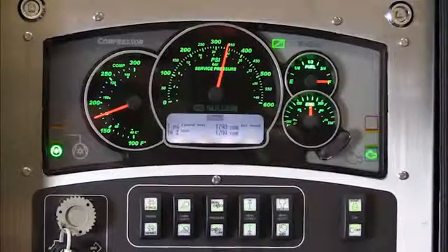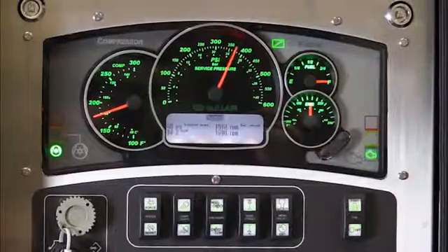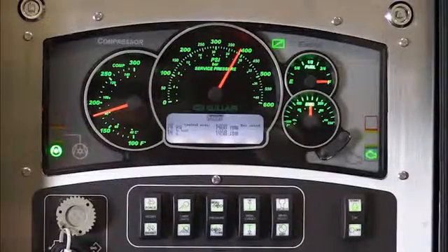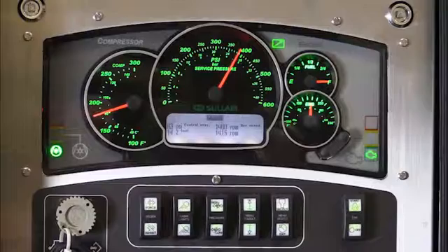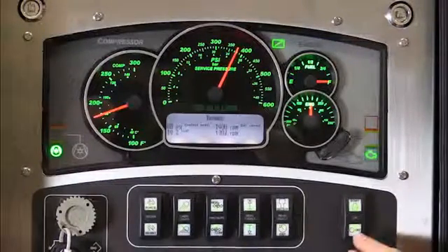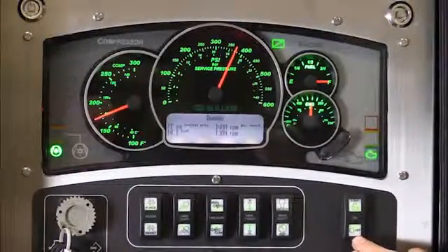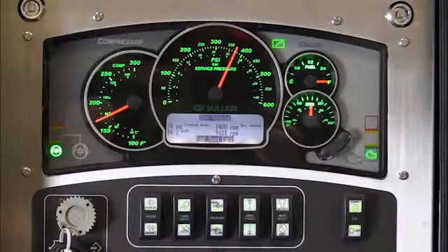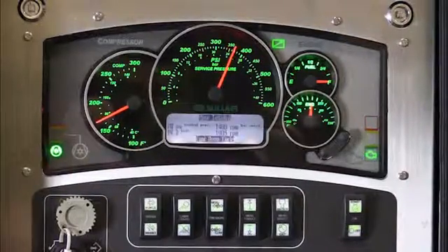We will now demonstrate the shutdown process. Take the unit from high to low. I close the discharge valve and turn the ignition switch off. The C-Pro then transitions from run mode to cool down mode.